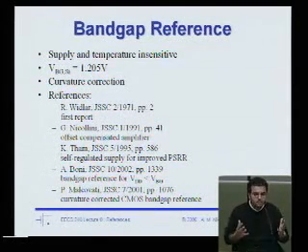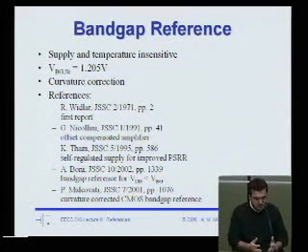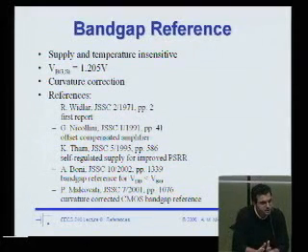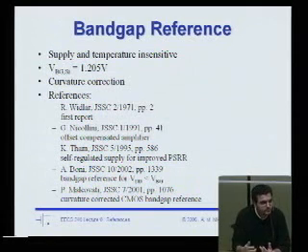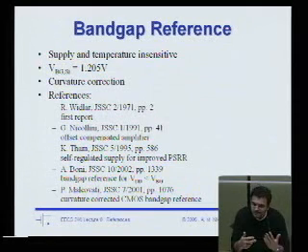So great. You can build a CMOS circuit or a bipolar circuit that generates a very constant voltage over process and voltage, and also over temperature if you have some curvature correction. That's great, but the problem is that we usually need currents, right? We need currents to start up our circuit. So anytime you generate a current, you have to use a resistor. And so that kind of messes everything up, right?